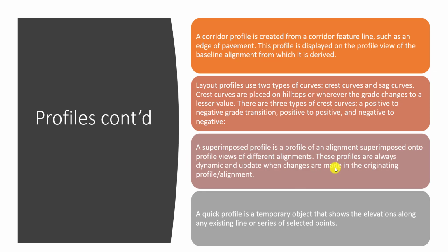So we will go over this because this is a nice feature. If you have shot the center line of an existing gully of your waterway, and you shot the center line of your proposed waterway, you want to show maybe if you have to do any filling on that gully in order to put your waterway in, or you don't want to do any filling, you want to have your center line of waterway below the existing cut.